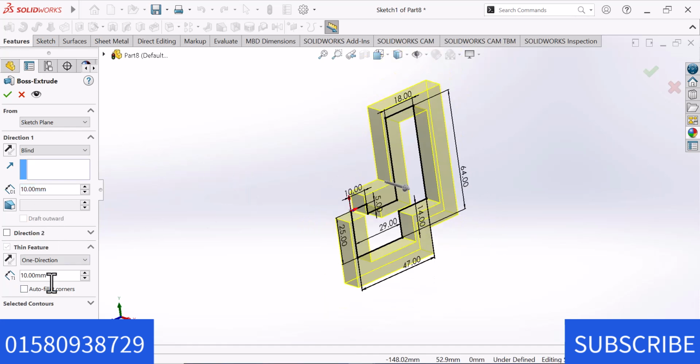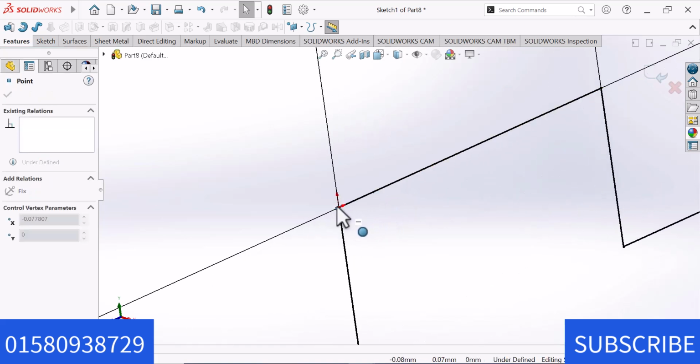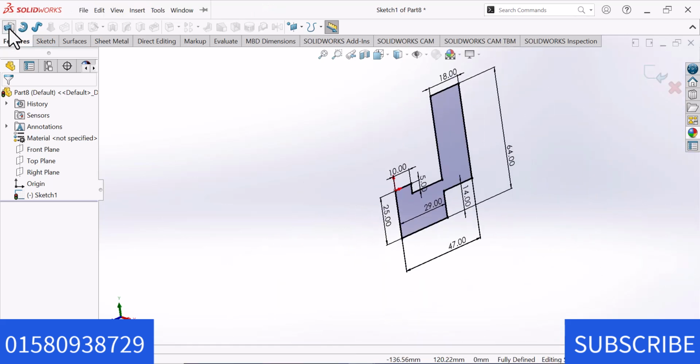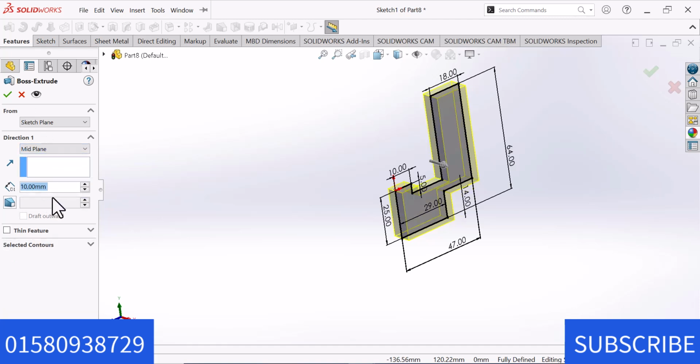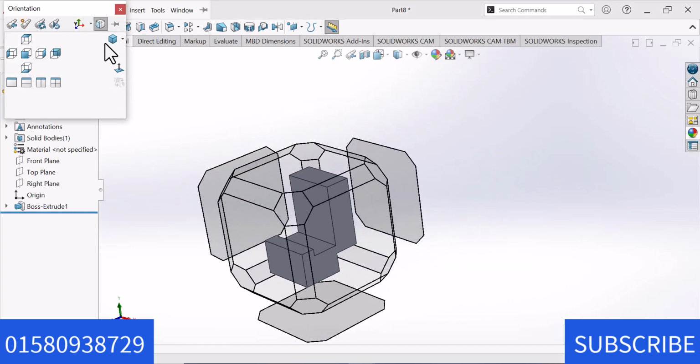Now here select contour. Select here. Now delete the thin feature. Now here, sorry, this point and this point connect. Okay. Now go to Feature and select Extrude. Extrude from mid plane. Now give the value here 40. Okay. Now go to isometric view.